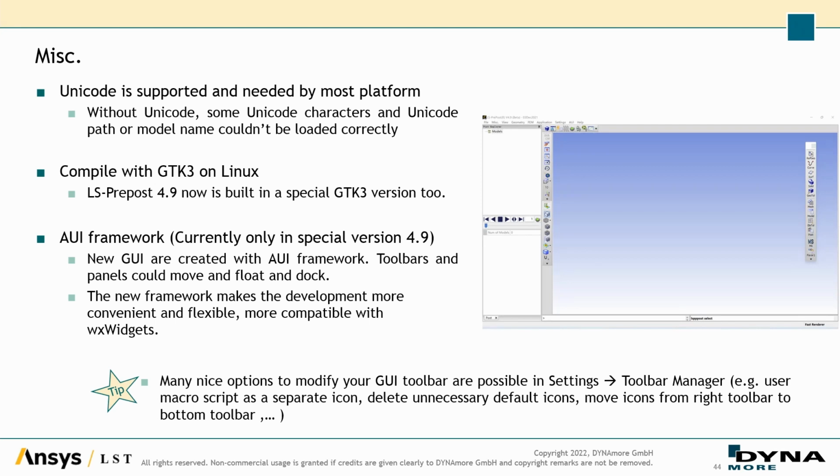My tip: there are also many nice options to modify your GUI toolbar design. For example, go to settings in the toolbar manager. For example, you can use separate icons with your user pictures for the icons, and your user macro script can be executed via this icon. You can delete unnecessary default icons. Perhaps it's too much and you don't need the geometry tools, for example, so you can delete it. Or you can move icons from the right toolbar to the bottom toolbar, and many more.